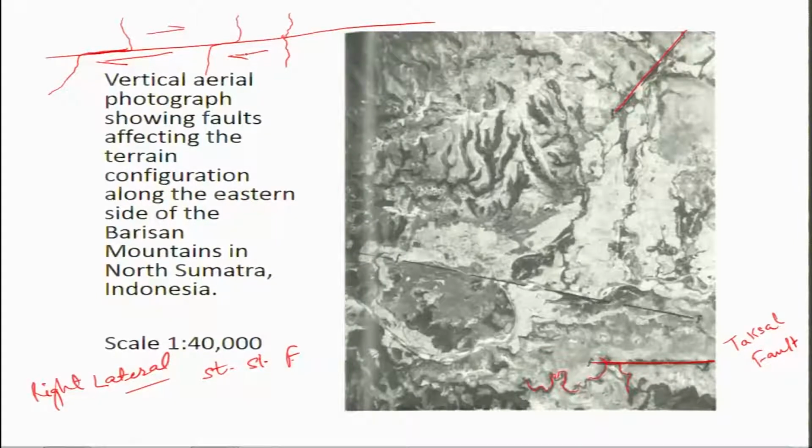So whenever there is an event, there will be some strike slip motion. So suppose in one event it moved around 1 meter, in two events suppose 2 meters. So we can also detect the number of events on a fault by quantifying the deflection pattern of different streams. Like this stream is showing the maximum deflection of around 3 meters, this is showing a deflection of 2 meters, it is showing a deflection of 1 meter. So it means that this is the oldest stream